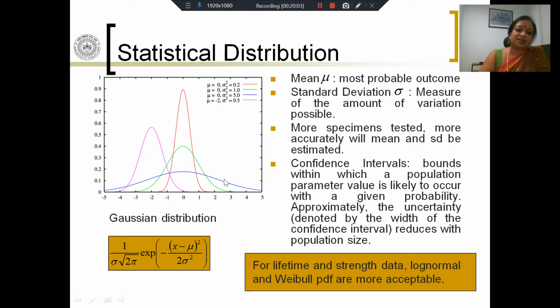You might think that in that sense, the blue curve is better because it is more uncertain. So maybe there is always a higher chance. If you look here, let's say this is a very high value of the over voltage. The blue does have a chance of withstand, whereas the red probably has no chance of withstand. But that is okay. This certainty is better because if you are certain about the manner in which your material is going to behave, it is easier to design for it. So we would probably prefer the material that is signified by the red curve.